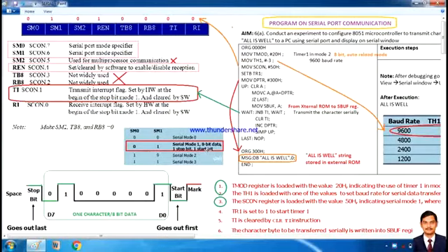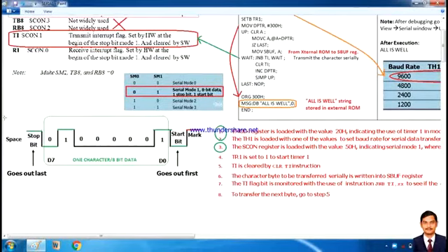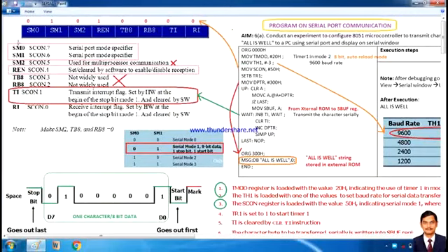It looks like this: the start bit goes out first, and the following bits are your 8 bits, one character at a time, which is 8-bit data. The last bit that goes out is the stop bit. In this way, it will be formatted. So by passing 0, 1 to this, it is set in this fashion.